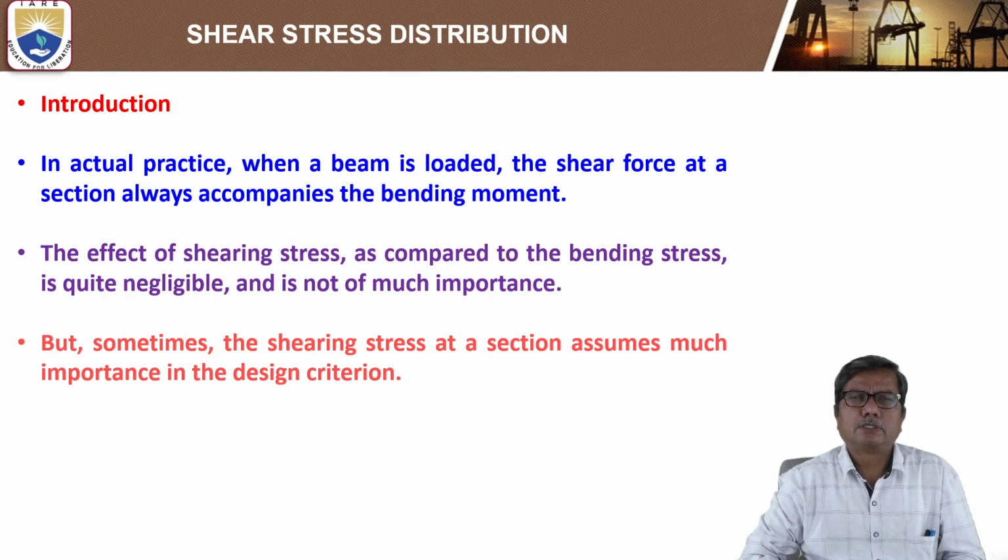Shear force on the cross sections, that is the tangential sections. Because of the transverse load, every cross section is subjected to shear force in combination with the bending moment also.